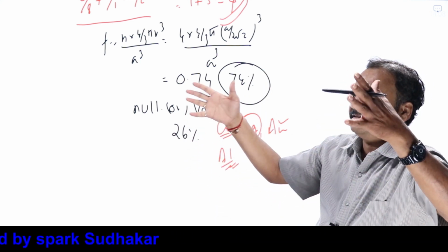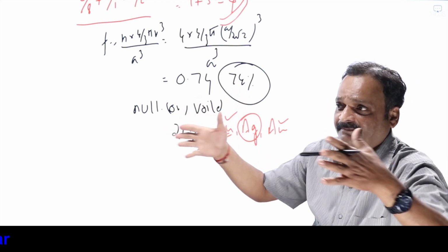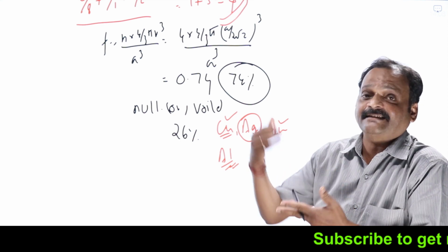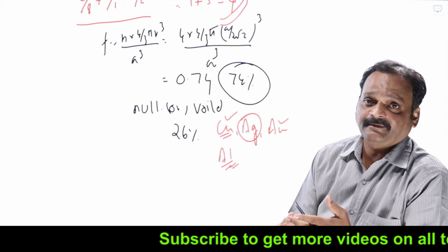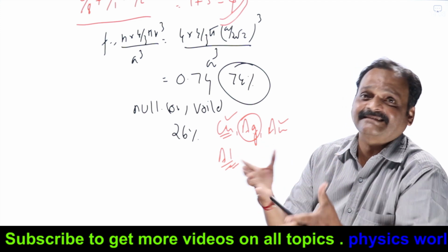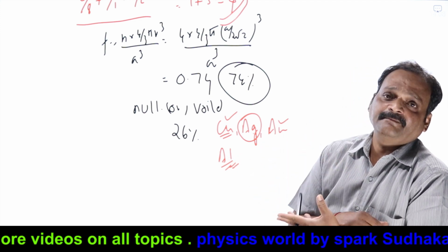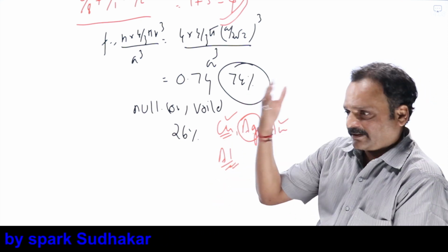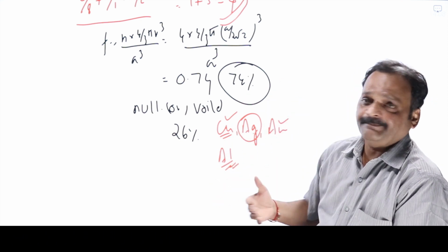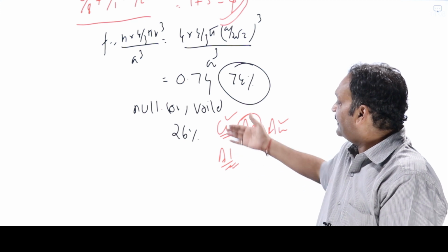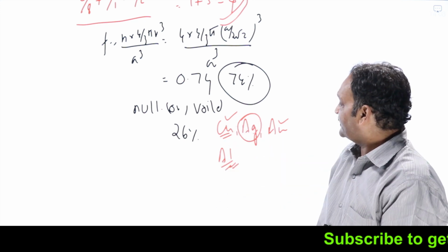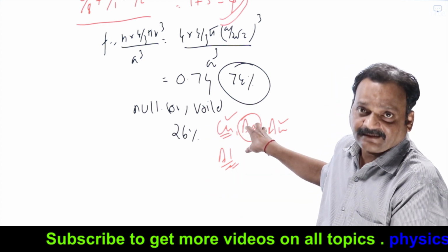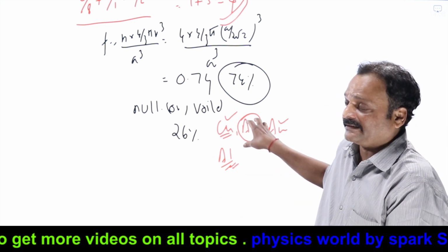For large industrial bus bars carrying hundreds of amperes of current, people prefer aluminum, though its current carrying capacity is less than that of copper, because its mass is less, so its weight is comparatively less. Copper has its own advantages. So copper and aluminum are widely used in the electrical industry for wiring, and silver is widely used as electrical contact material.